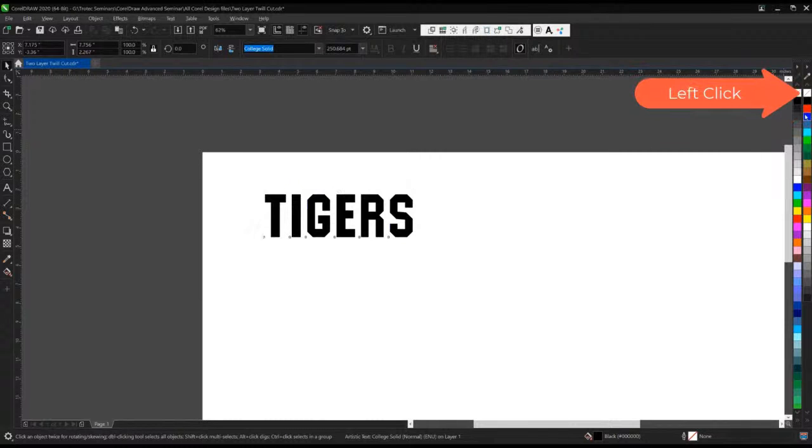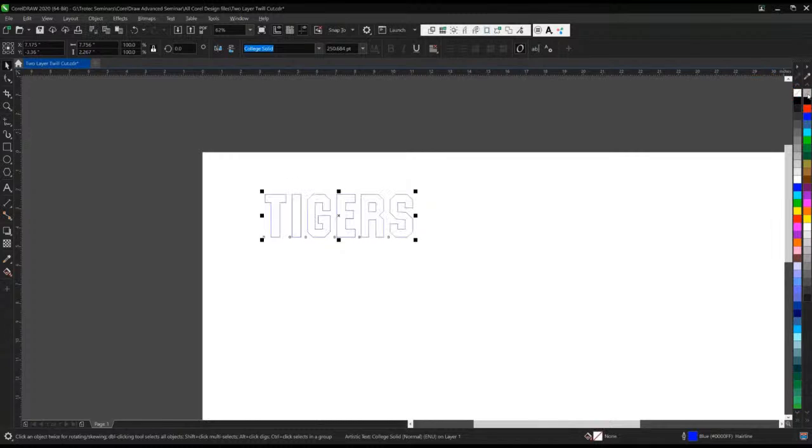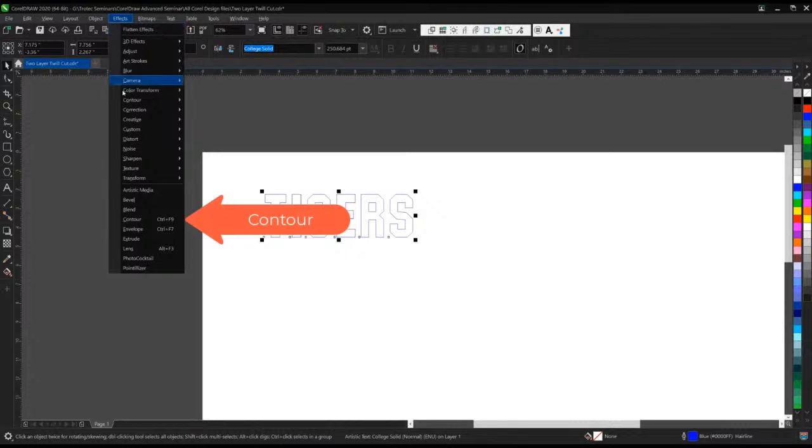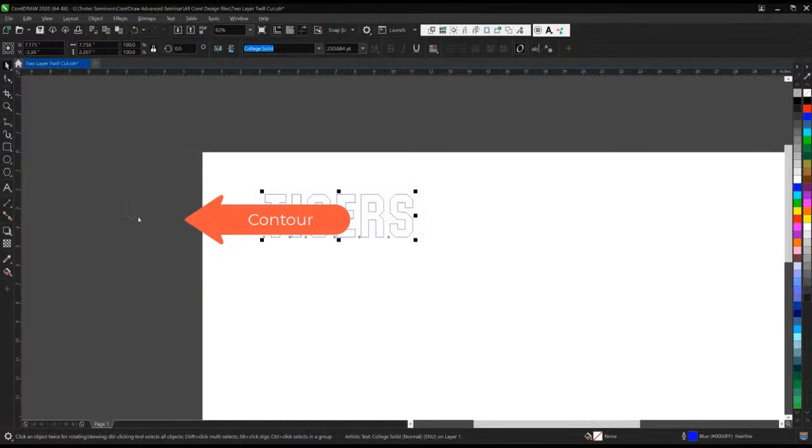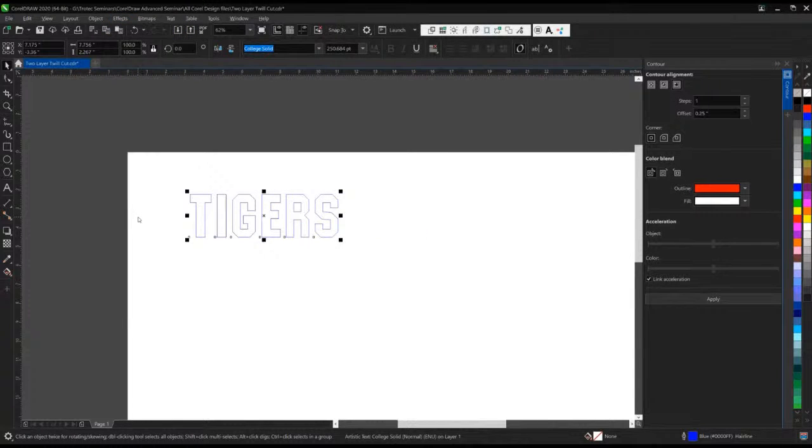Let's go ahead and right click on blue, left click on the slash at the top, and get rid of our fill. The reason I'm doing blue is because I want blue to cut through one layer, and then I will use red to cut through both layers. And that's what color does for you on a laser. Color is a different operation or process.